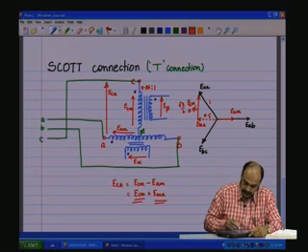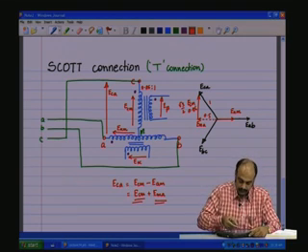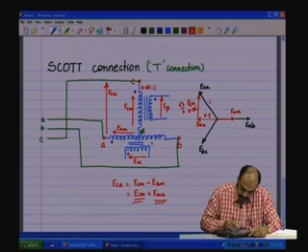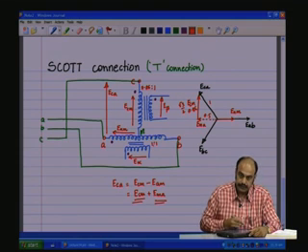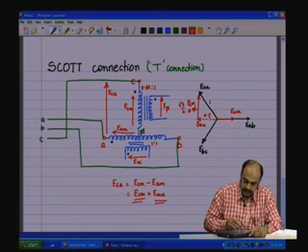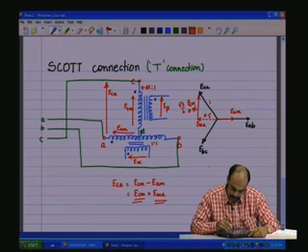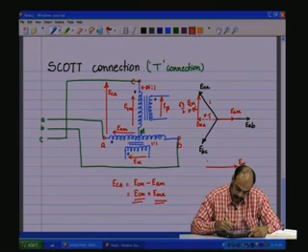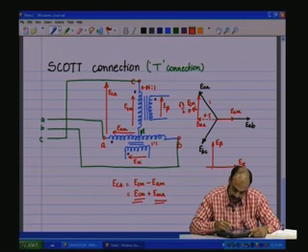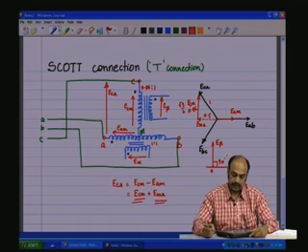So, E alpha is nothing but EAB, and we could have, let us say, 1:1 turns ratio. Now, this gets stepped up from 0.86 to 1 and you have E beta. So, we have E alpha along EAB and then we have E beta along this direction. They are 90 degrees with respect to each other, they are orthogonal.